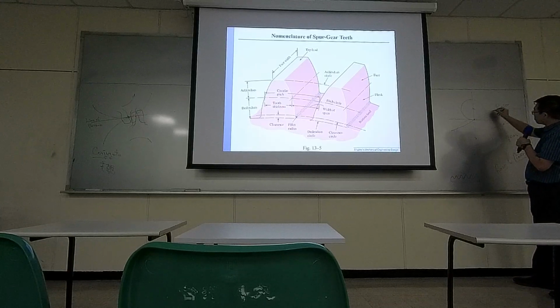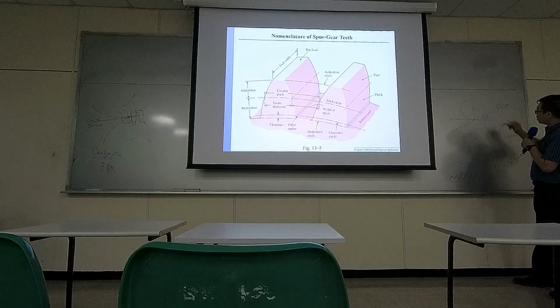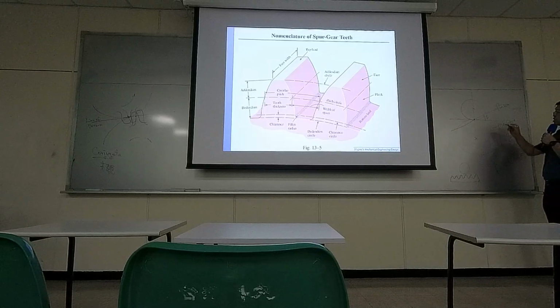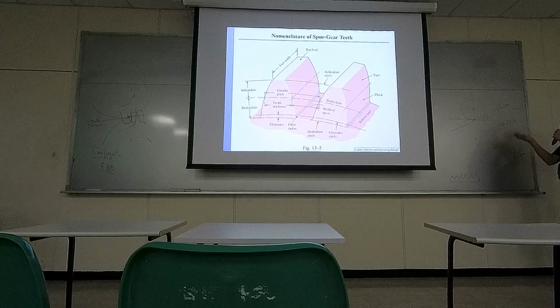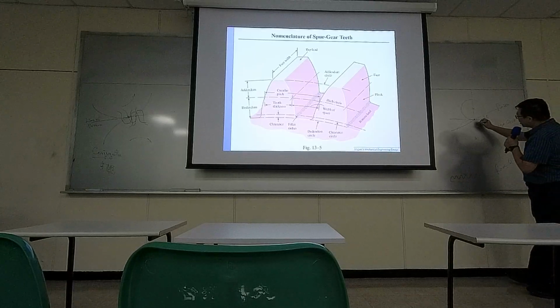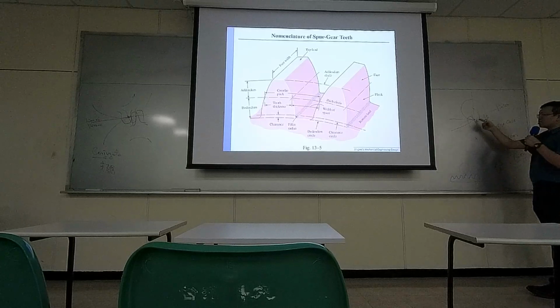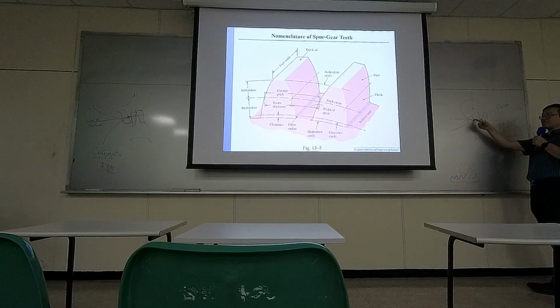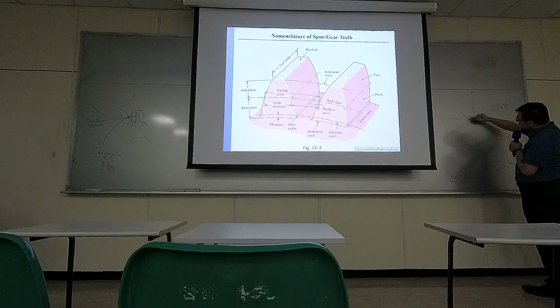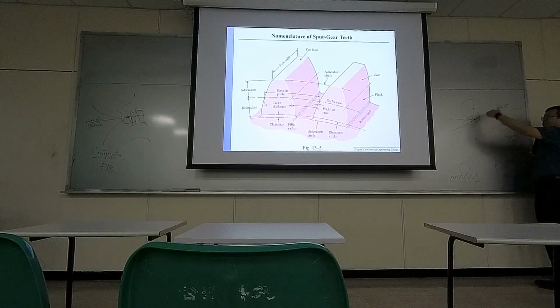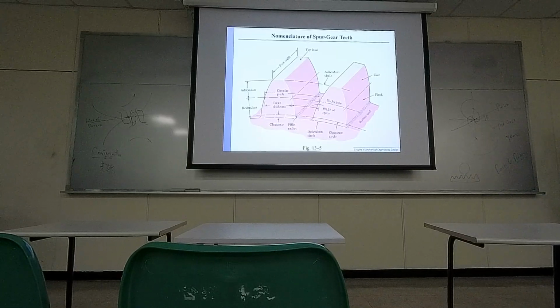And usually you'll see something like this, showing you an angle. So basically that is the line of pressure. So this is basically the pressure angle. If you see a drawing like this, it is indicating that when the gears interact with each other right at this tangent point, the pressure between both of them follows this line of pressure.